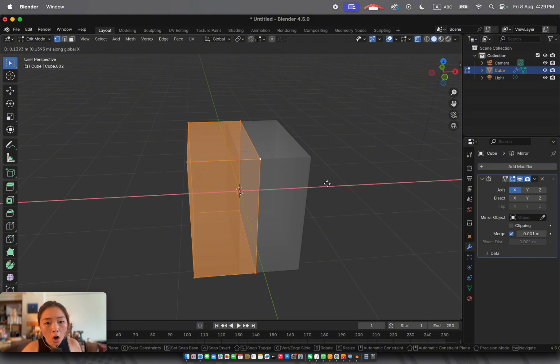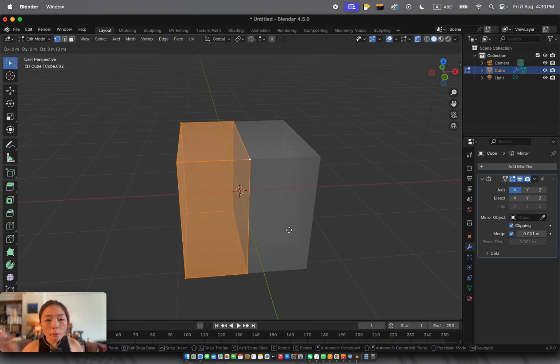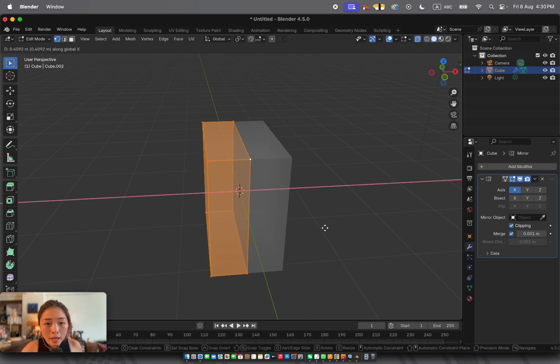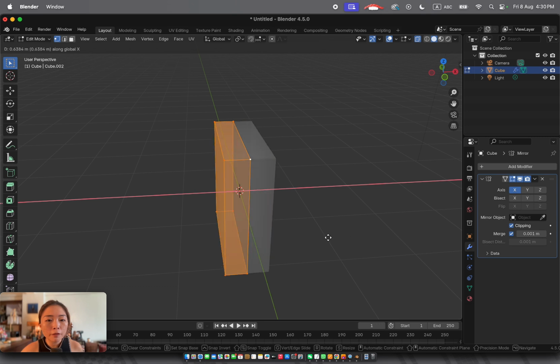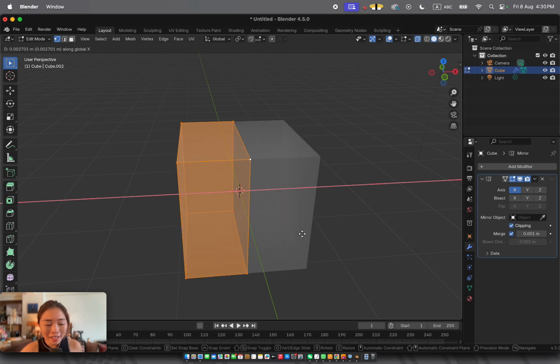And if I turn on the clipping, and if I now move the left half of the cube to the right hand side, let's see what happened. Grabbing on the x-axis. Now you see in the center there is no darker gray in the middle when it's overlapped because it is not overlapped. Now the entire mesh is stuck to the other half without overlapping any faces to each other. This is one thing to prevent: you have overlapped faces for weird shading and texturing.